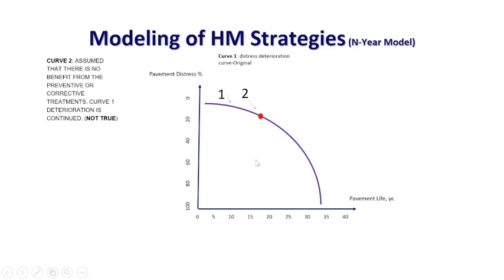Say when you have this second one, you can model it assuming this thin overlay really brings up the performance, right? You bring it up, and then the combined thin overlay and underneath thick overlay perform exactly the same way as the underneath pavement. Okay, do you think this one is conservative or aggressive? I believe it's very aggressive. I think it's a little bit aggressive.